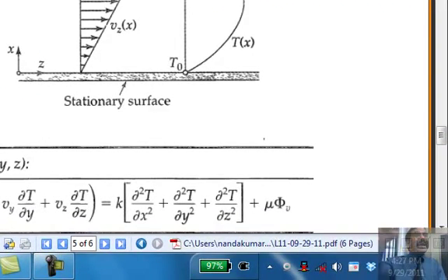So what we are going to do is analyze this problem in the limit of very large radius and very small gap. The gap between the two cylinders is B, and B is very small. So I'm going to ignore the effect of curvature. It is exactly like two parallel plates. So I'm focusing only on this zone, as if I'm stretching it out.